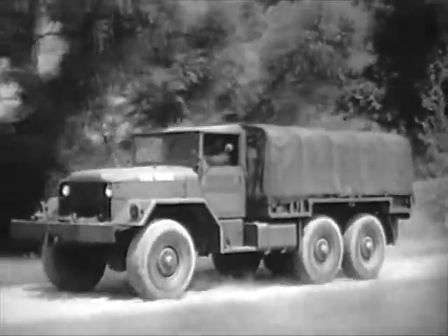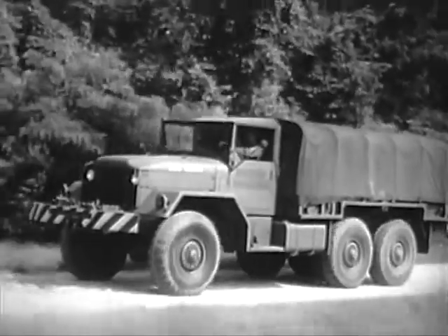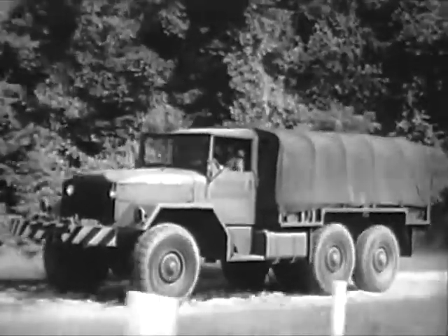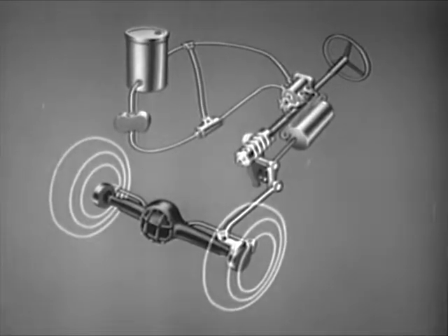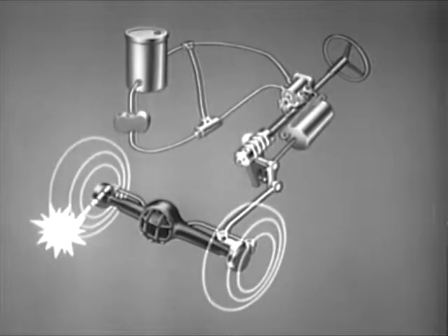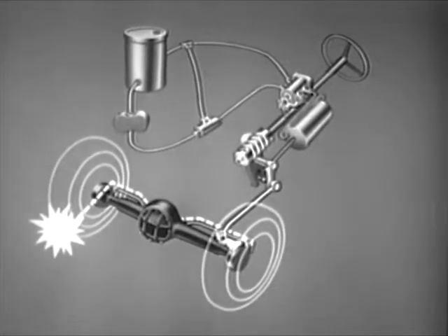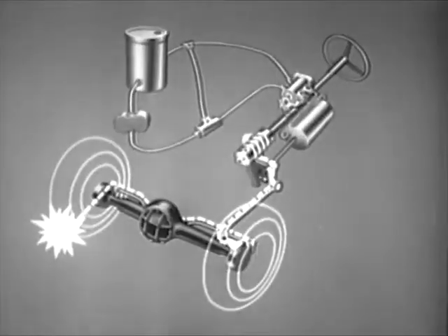One of the steering problems of the heavy vehicle with cam and lever steering is road shock. Road shock causes kickback of the steering wheel and makes control of the vehicle difficult. On the other hand, heavy military vehicles equipped with hydraulic steering resist road shock through a reverse action in the power cylinder. When one of the front wheels is subjected to road shock, the shock is transmitted through the steering linkage to the Pitman arm and the Pitman arm shaft lever. The Pitman arm lever then actuates the cam, causing it to move up or down depending on which wheel receives the shock.